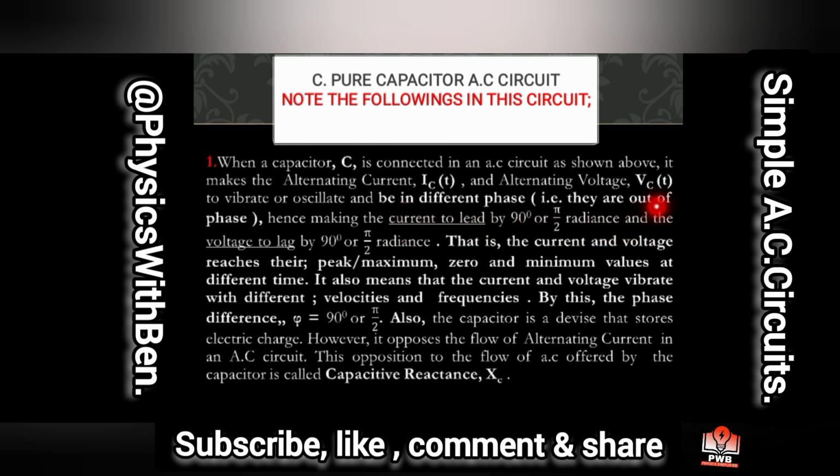They are out of phase, hence making the current lead by 90 degrees or pi over 2 radians, and the voltage lag by 90 degrees or pi over 2 radians. That is, the current and the voltage reach their peak, maximum, zero and minimum values at different times. It also means that the current and the voltage vibrate with different velocities and frequencies. By this, the phase difference phi is equal to 90 degrees or pi over 2.